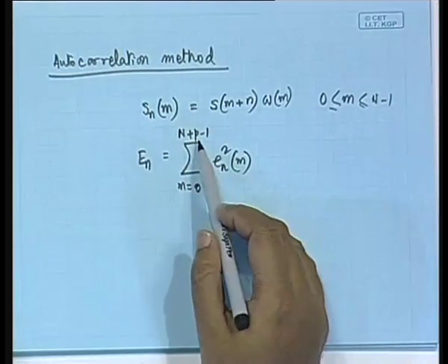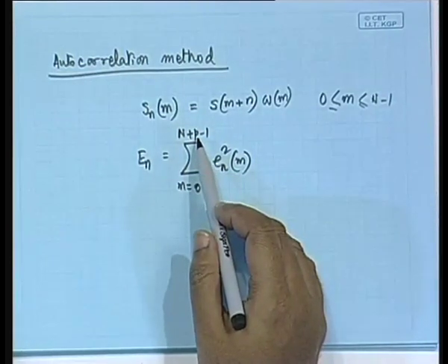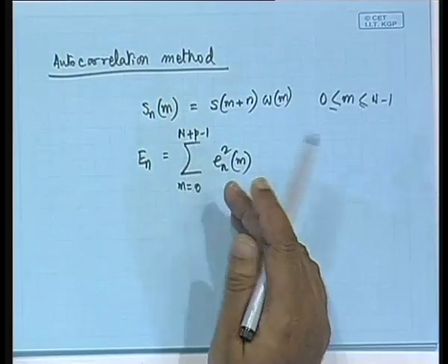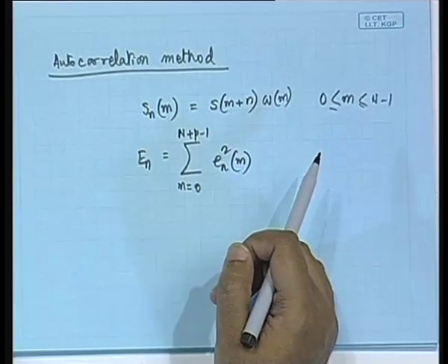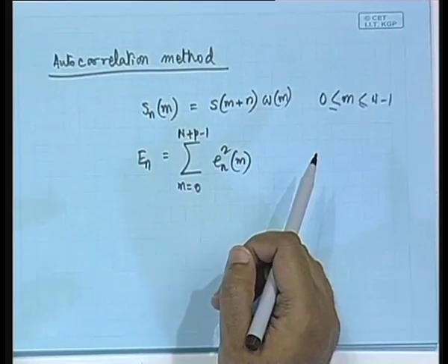So, there is an N plus p term which has come about, and why is this N plus p coming in? Because whenever we are taking the autocorrelation, it will be from p samples, since we are predicting. So, if we give a lag of p, we need to have this N plus p minus 1, those many samples we require.